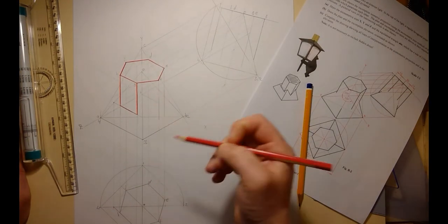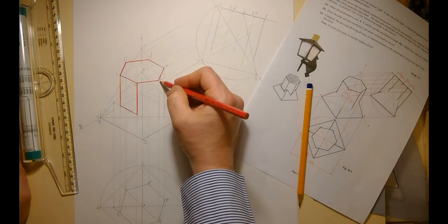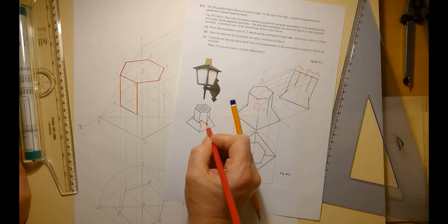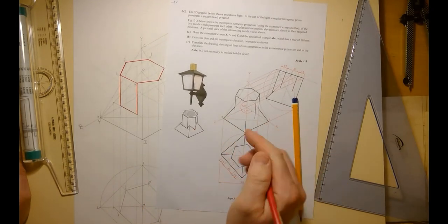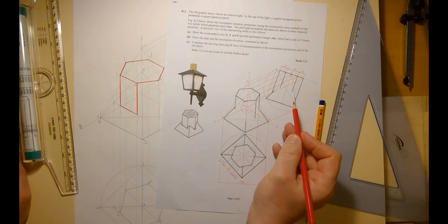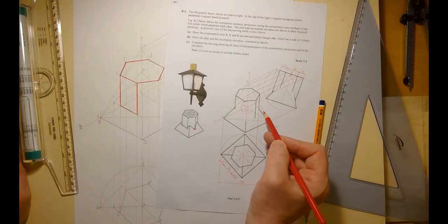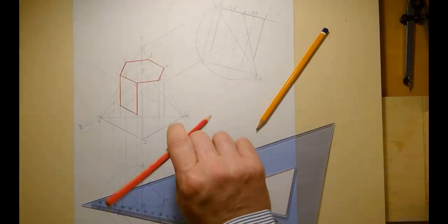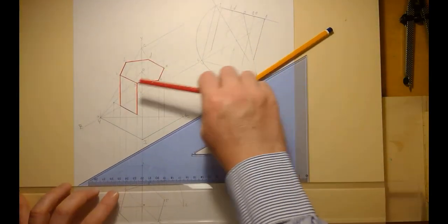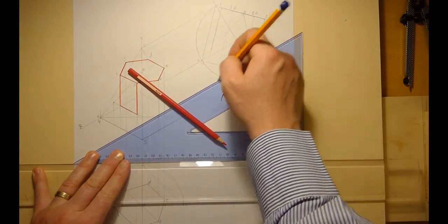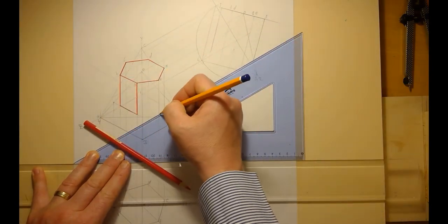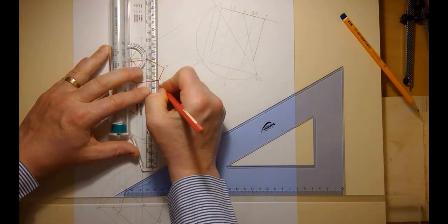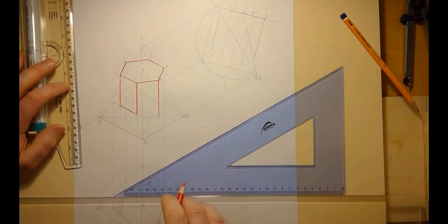Now if we were to look at the next point, say on an actual proper edge, which would be the one from F down along. So where does this finish down along here? That's easy enough to find, because that crashes straight into that face there. And I can just project that straight down there from my elevation, and it's going to cut that off for me. Okay, just get that out of the way. So just project down at my 30 degrees from my elevation, and that shows me it cuts it off right there. So again, I'll just put that in red as well. Okay, so that's that point found. That was grand, that was handy.